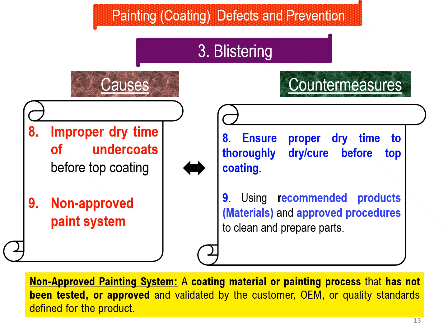Number 8. Improper dry time of undercoats before top coating. Ensure proper dry time to thoroughly dry and cure before top coating. Number 9. Non-approved paint systems. The recommendations are: use recommended products, materials, and approved procedures to clean and prepare parts.